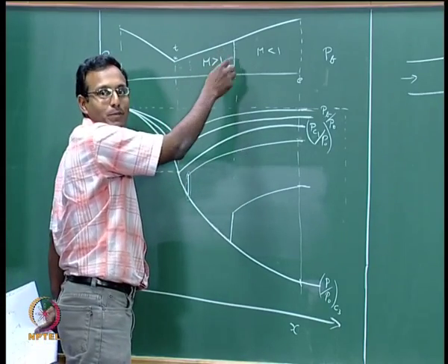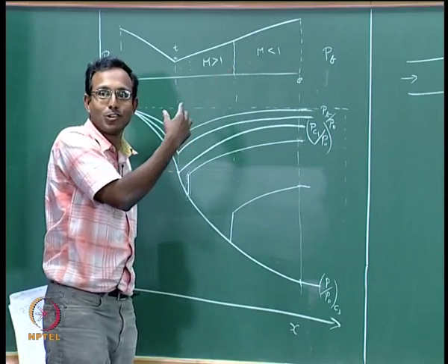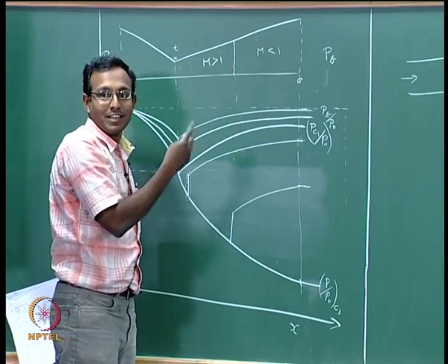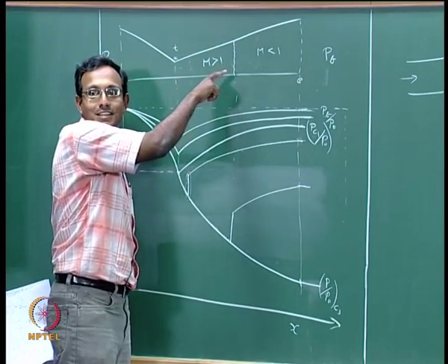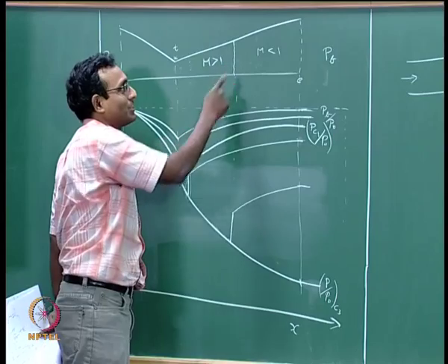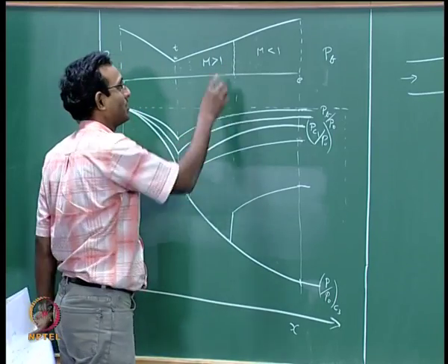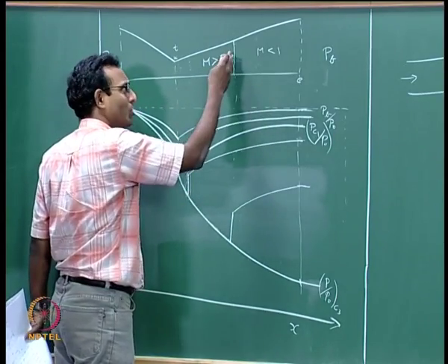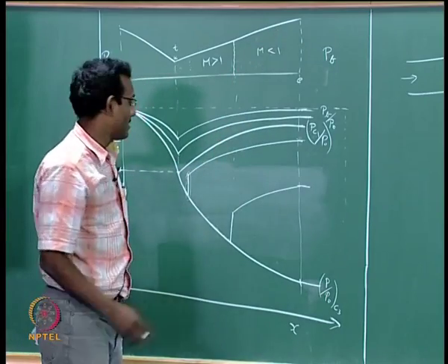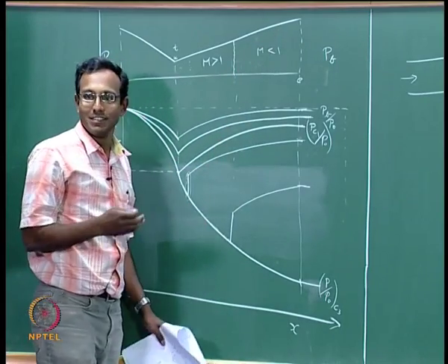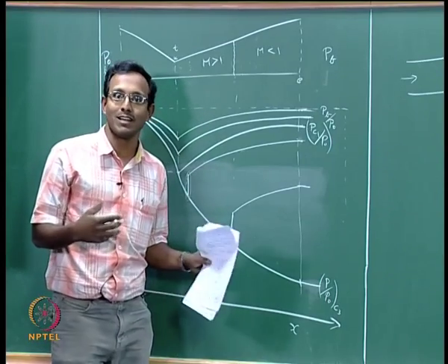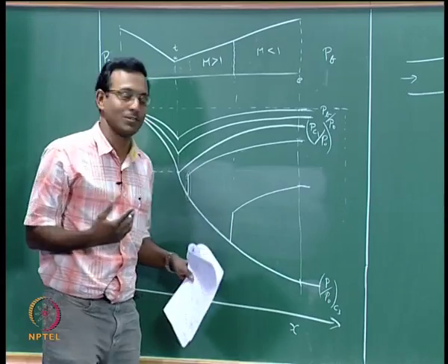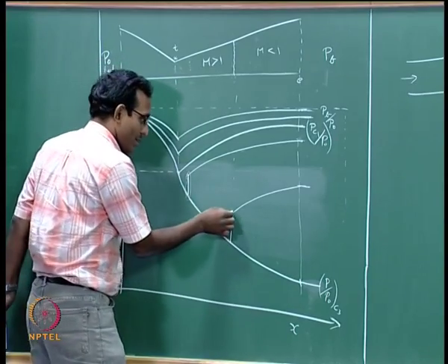It goes there, the shock becomes stronger and stronger, and the Mach number of the shock gets higher, it can run faster. But remember the flow is also getting faster, it will go and sit at a new point where they are going to be equal. That is where it sits. If I decrease too much the shock will go more out. This is one nice way of thinking about it. This kind of expansion and compression waves moving around helps you a lot in getting a physical feel for the problem.